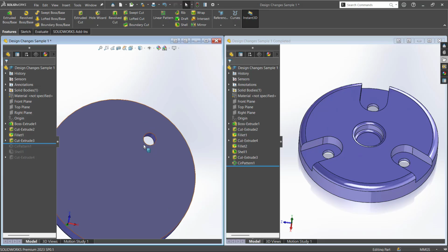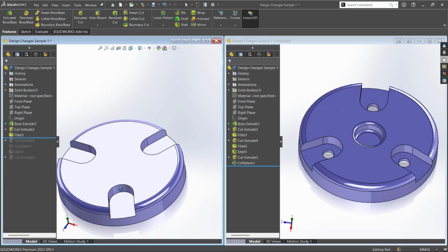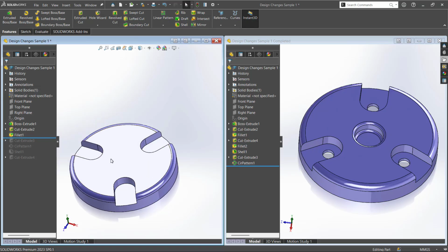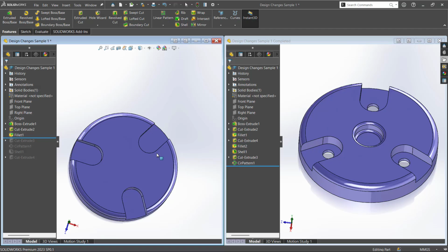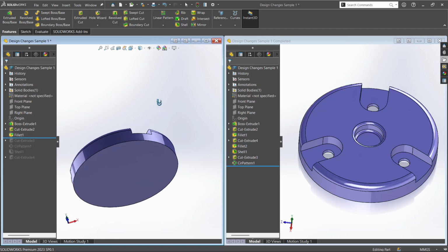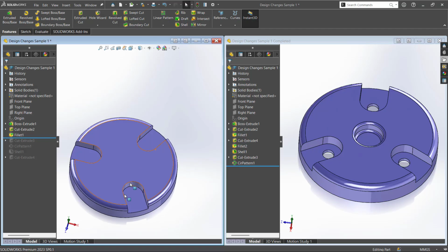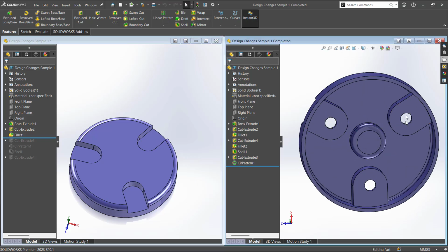So what is the best way to tackle this? I should not have any of the holes here first. So what we can do is just slide slightly up, and now if I create the shell feature, it will only create the shell for these features. Am I right? And then later if I create the holes, I won't be having the shell thickness captured for that. So what do we do now in this?